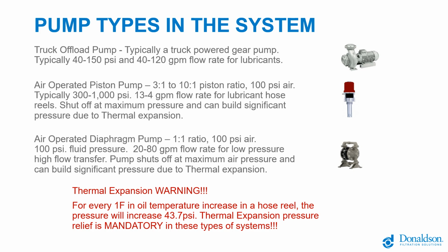The manufacturers of these pumps have gone from a warning to a mandatory requirement to install thermal expansion pressure relief systems on these pumps. If they start seeing pressure above the shutoff pressure, they open up a valve and bleed it back into the tank, and you really want to make sure that's there, because the hose reel can burst, the nozzle trigger can burst, or even the filters can burst. It's overpressurizing the system well beyond what it's supposed to for use in these.